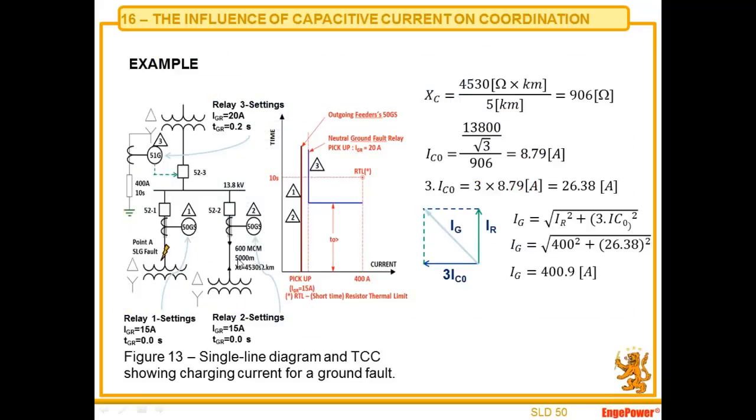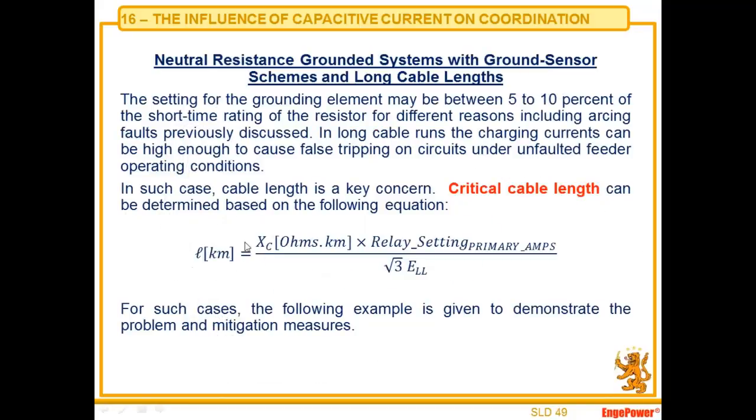And the critical cable length: if you have a length lower than the one calculated here, probably you won't have a problem. But if your conductor lengths are greater than the value you calculated here, you are going to have problems. So this is the critical length to be a base for you in order to take care of this situation I explained right now.